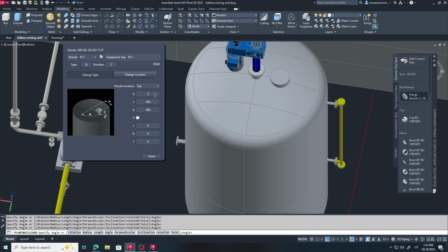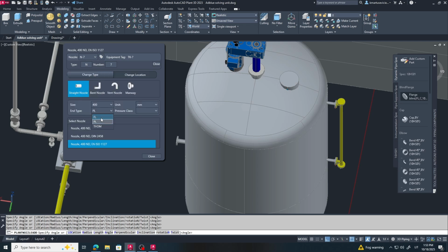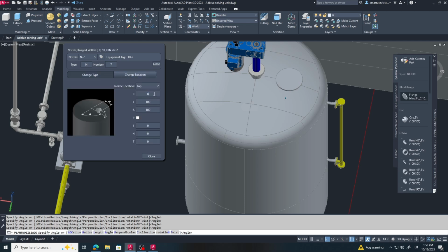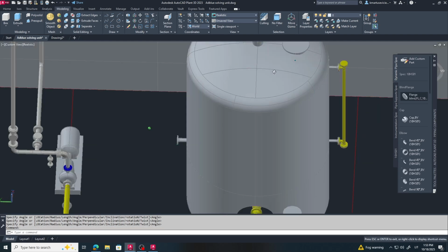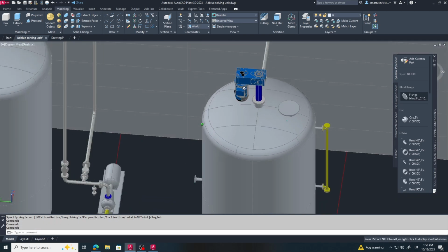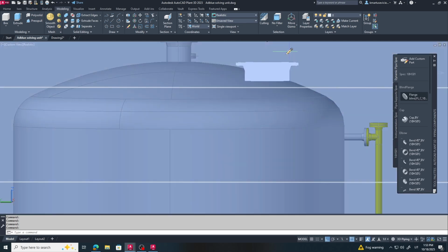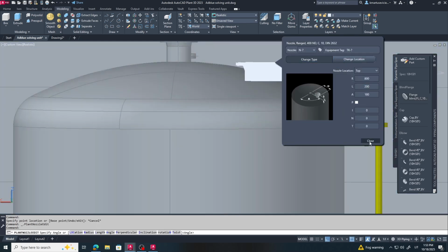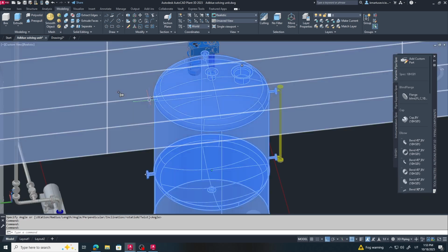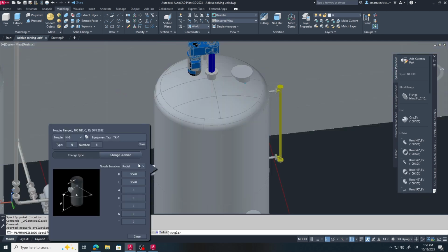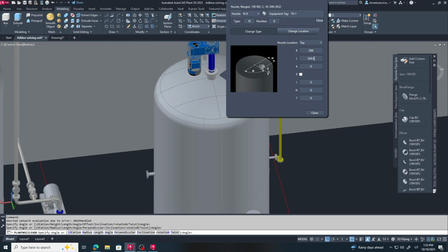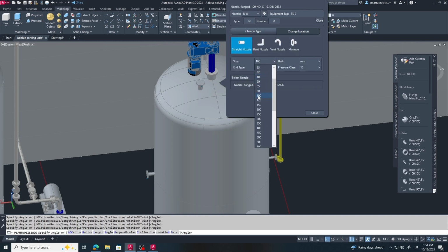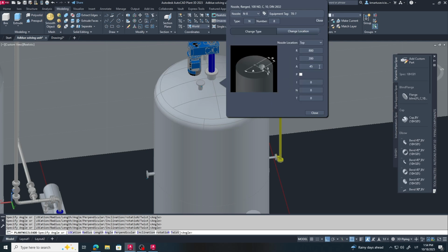Now I'm adding a simple nozzle for carbamide urea powder. In real AdBlue production, the dry urea is usually transported to the reactor by a screw conveyor. The conveyor feeds the powder directly into the top of the vessel through this dedicated charging nozzle. The job of the nozzle is straightforward. It provides a sealed, controlled entry point for the powder so it doesn't spill, create dust, or contaminate the area. Once the powder enters the reactor, the agitator immediately starts dissolving it into demineralized water, helping us reach the correct concentration.